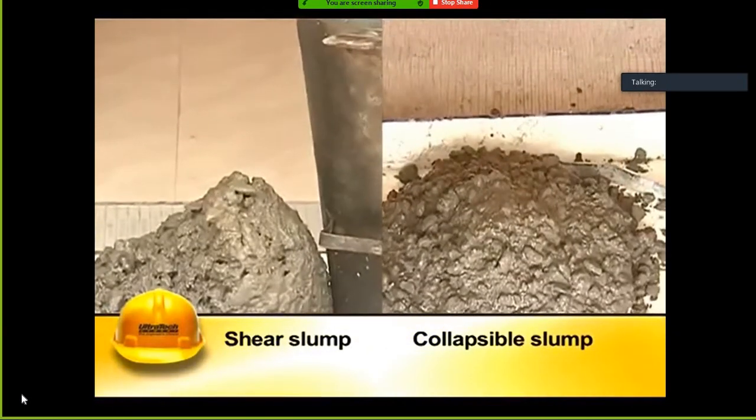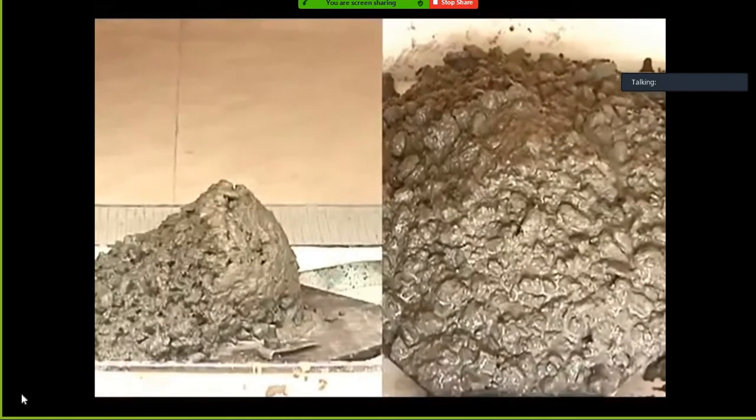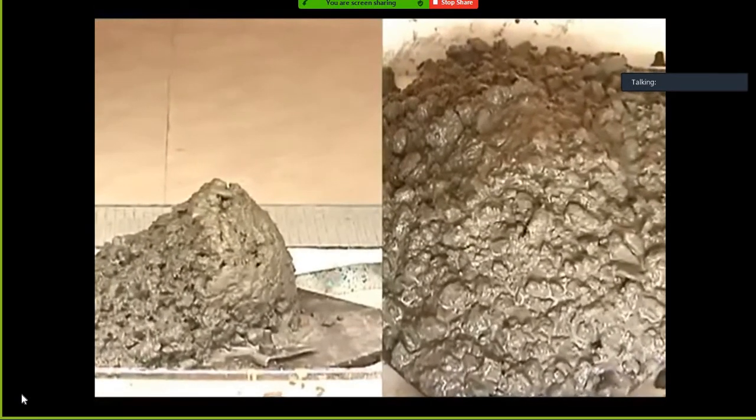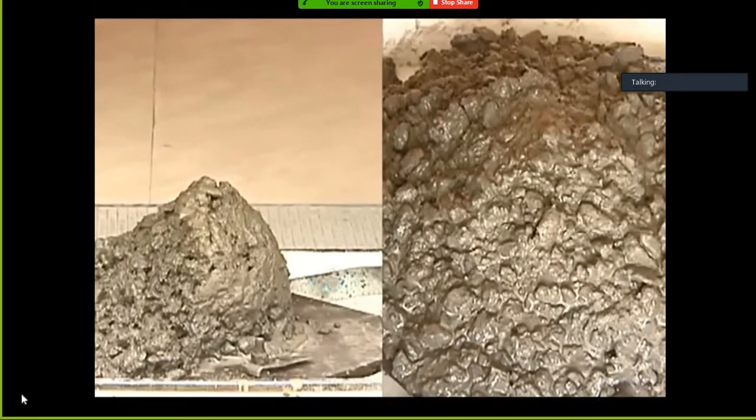In case of slump results beyond the specified limits, the mix proportion needs to be adjusted, especially the water content. The slump can also be varied by changing the proportion, size, and combination of the various sizes of the aggregates.